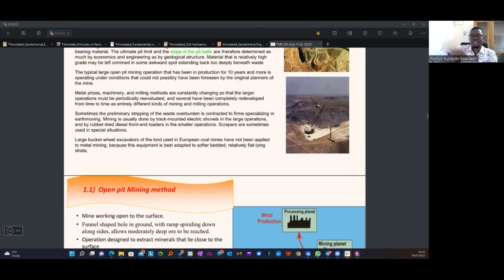Because if that excavator was supposed to load a truck within 3 minutes as of that time, now you've changed the truck, it's way higher than it. It gives challenges to an operator who is operating it, and then it takes so much time. Even sometimes the bucket size of that excavator will have to do a number of passes. When I say passes, they're fetching the materials and dumping into the truck, coming back, dumping.